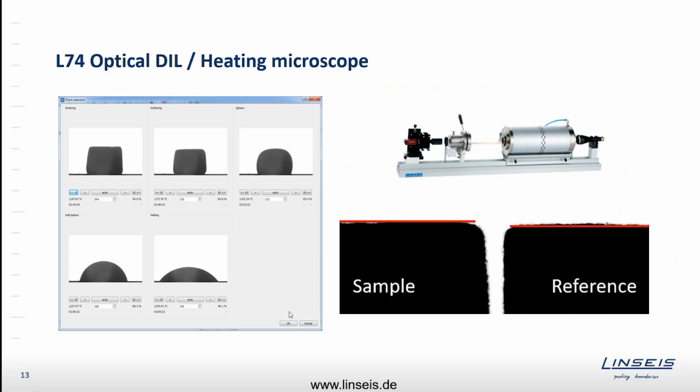On the left side, you see the so-called heating microscope mode. Using that mode, you have no filters, you have just the camera, and the camera has a viewing angle of 2 × 2 centimeters. So you see the complete sample piece, and then you record the sample piece completely, so in 2 dimensions, X and Y axis, during heating, during cooling, whatever you do. Typically, it's melting studies, it's contact angle and surface wetting studies. So you see in that example here, a sample that's melting.